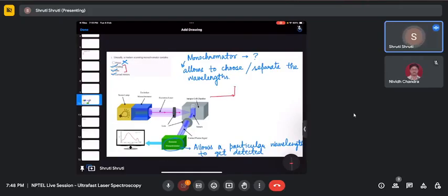You can put it like 10 scans, so you will have something like this 10 times, and then you will get an average of all the scans. So this is the average. So this is averaging time. So how many scans you want to average out?